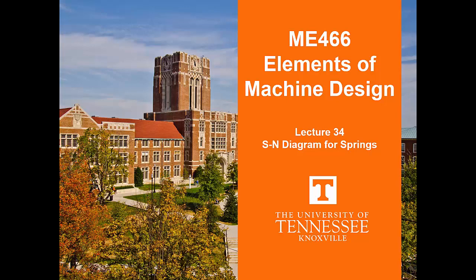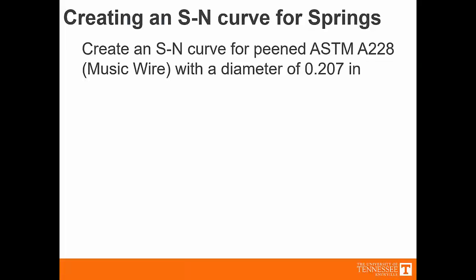In this lecture, we're going to take a look at the process of creating an SN diagram for springs to consider springs undergoing fatigue stresses. So to do that, we're going to illustrate this with a problem. We're going to create an SN curve for a peened A228 wire for a spring with a diameter of 0.207 inches. The first thing we're going to do is find out whether this wire can be made.